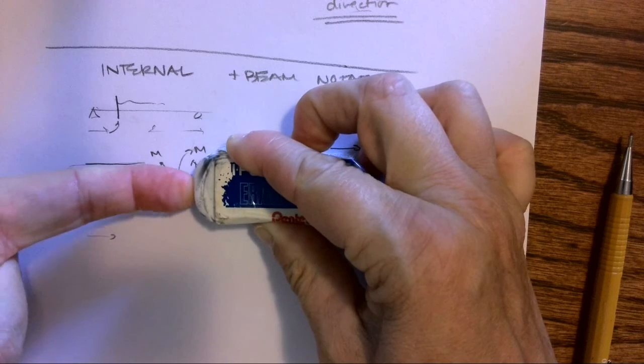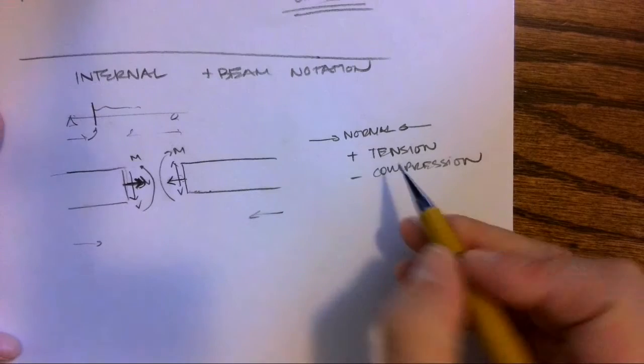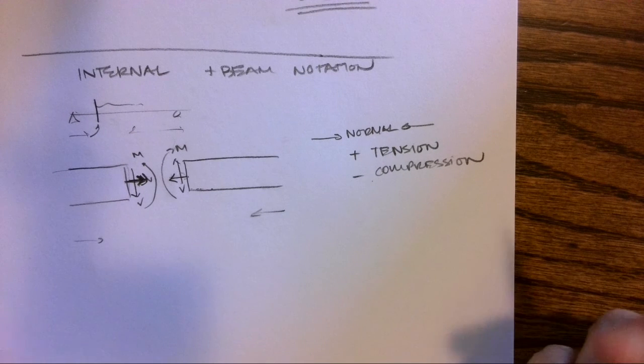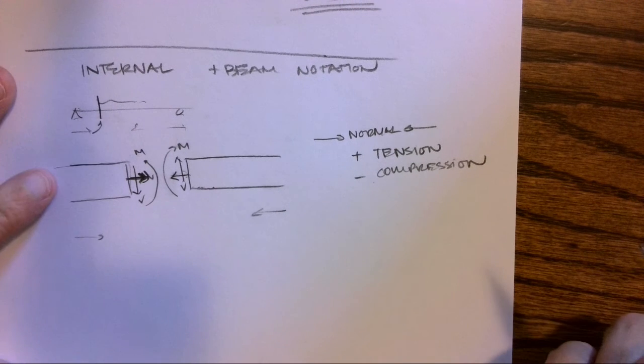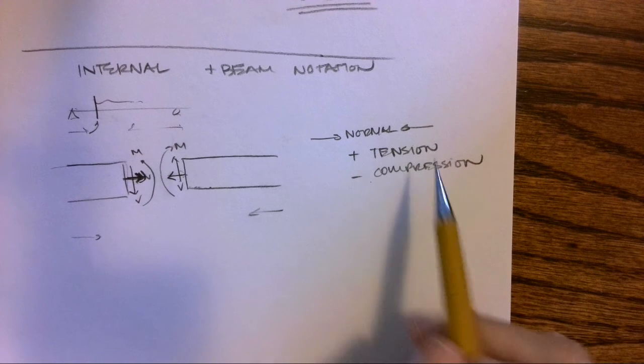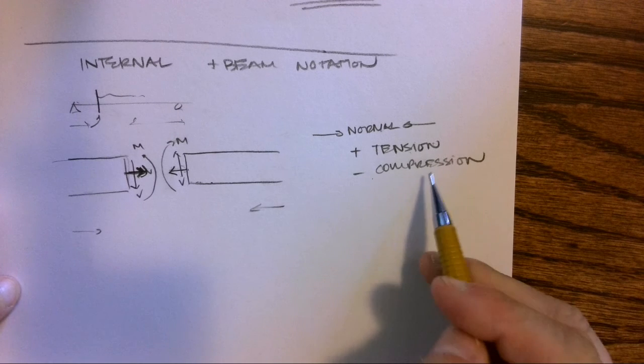So again, that's why you cannot have a direction. That's going to be compression. So if I said it was negative 20 kips, then you and I both know negative means it's a compression member. It's like a column. It's being pushed, as opposed to a cable, which might be in tension. Trusses are going to have both tension and compression.